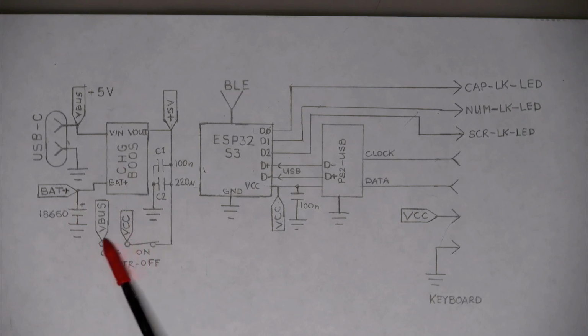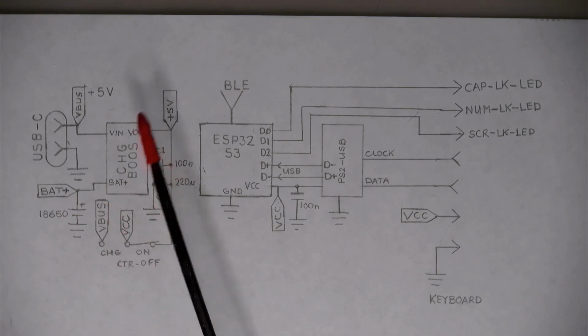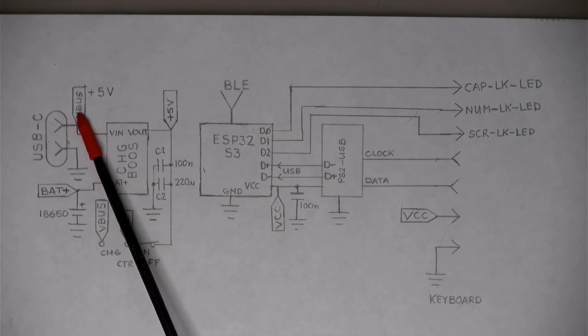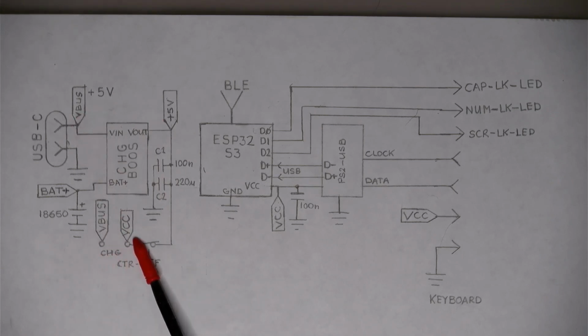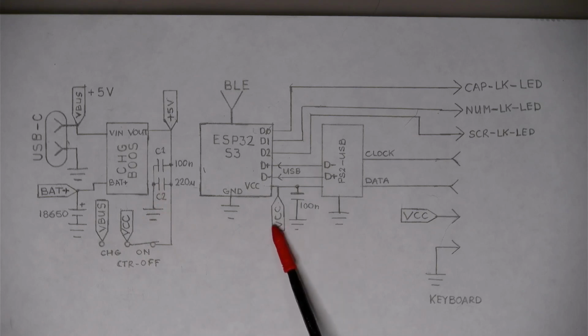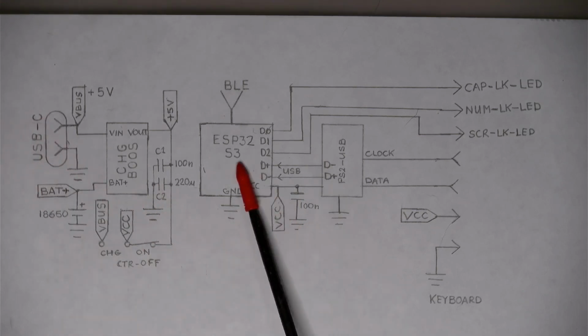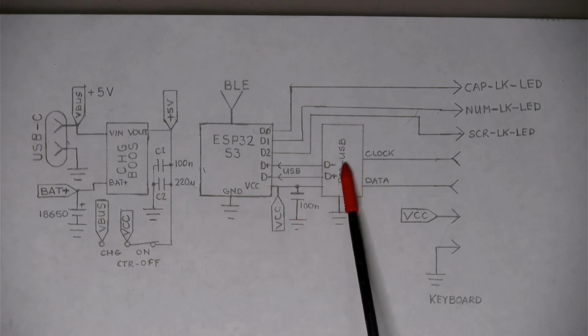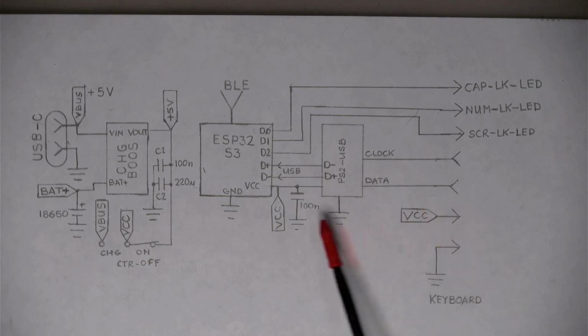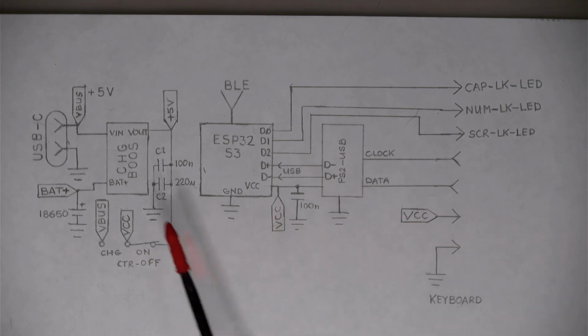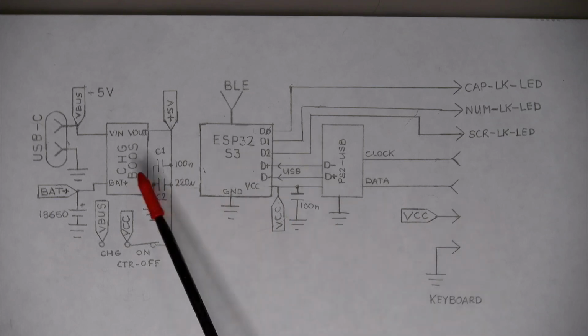If the switch is set to this position here, it will take the D-bus plus 5 volts and connect it to the VCC, so the USB-C charger is powering the microcontroller as well as that little converter board, and the keyboard is being presented there, so it's running everything, and the V out from the charge board is being ignored.